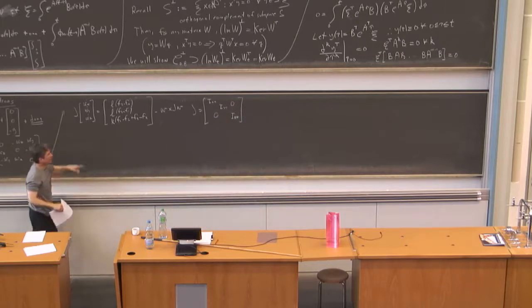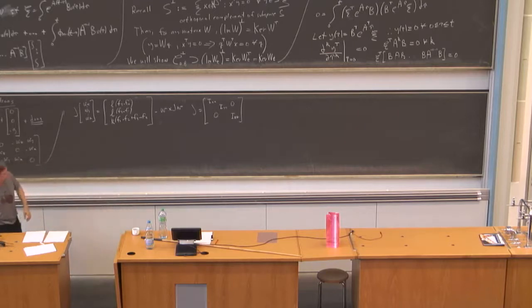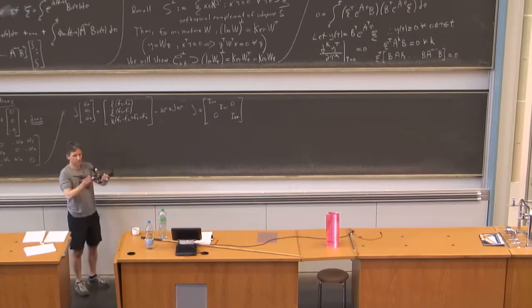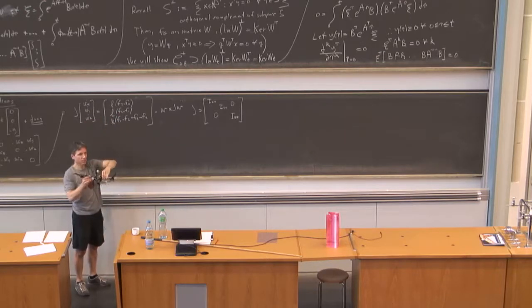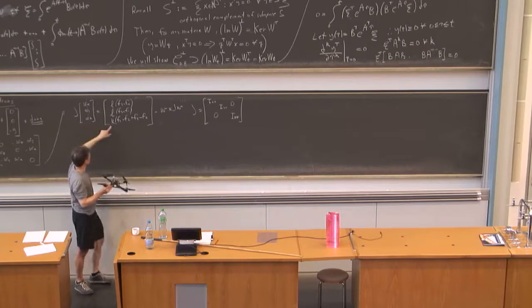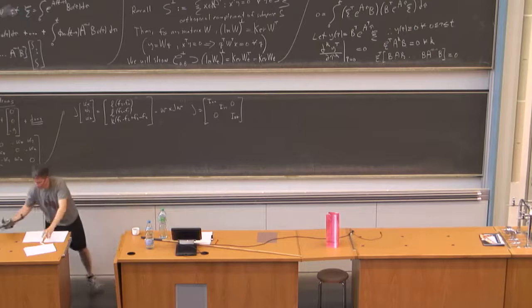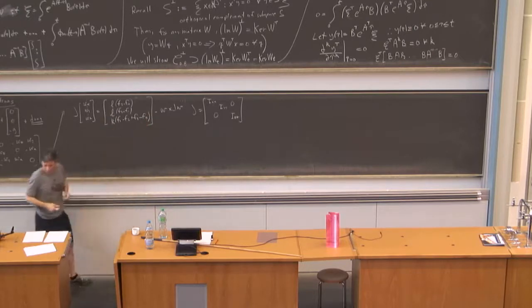And what is this capturing? It's basically what I said a little bit earlier. If I want this thing to roll, F2 minus F4 gives me the difference that allows me to apply a moment. If I wanted to pitch, F3 minus F1 allows me to apply a moment. And if I wanted to yaw, I have to get all 4 of these involved to apply a moment without affecting the roll and the pitch.